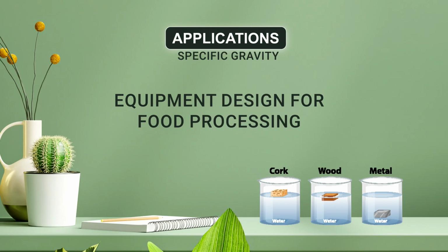One particular substance is settled in the bottom. The second one in the middle is completely floating. And the third, in the last, you see is half floating, half sinking. So if, for example, I just give you the example of a specific gravity of a material 0.8. Suppose there is a solid material which is of specific gravity 0.8. If you put it in water, 80% of it will sink, 20% of it will float.